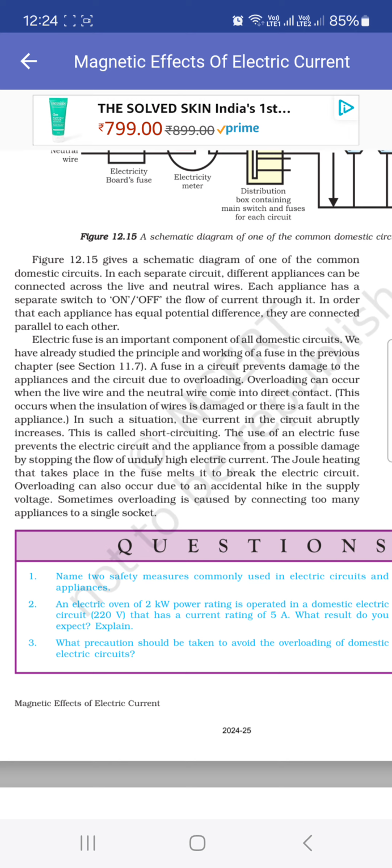A pure copper wire cannot be used as a fuse wire. Why? Because it has a high melting point due to which it will not melt easily when a short circuit takes place. Fuses are also used to protect the individual domestic electrical appliances from damage which may be caused due to excessive current flow through them.